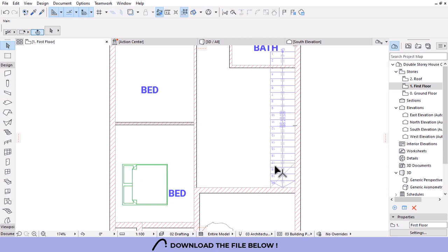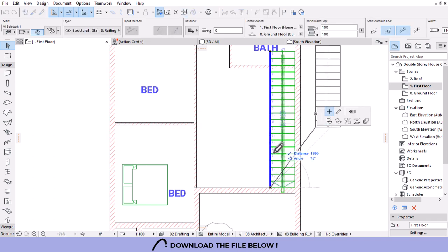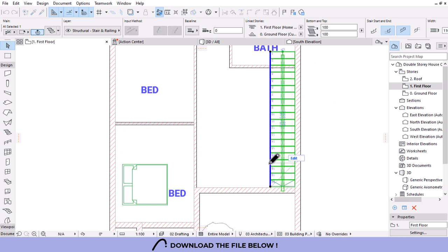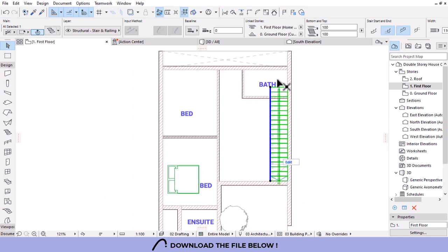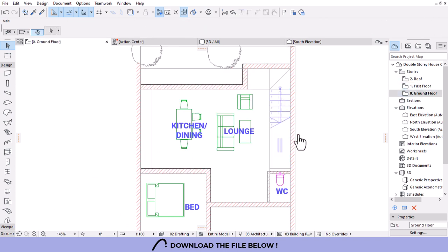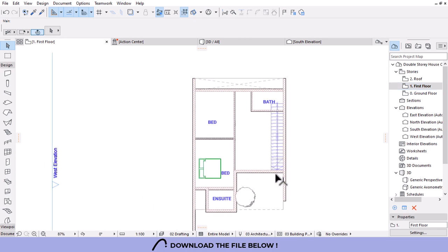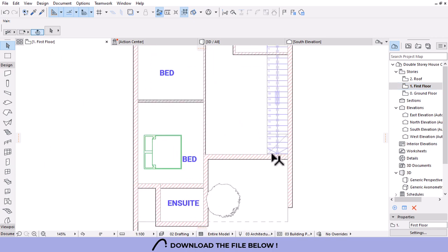We're having an issue here to resolve for the staircase, because if you look at here, we're supposed to have a landing or a starter for the landing on this level. So if I stretch this to here, let's see, but the linked story for this is the first floor, which is fine that way. So I think if we check on the ground first, it starts here and then goes all the way. On the ground is fine. So if you go on the first floor, we need to have an allowance where this is going to start.